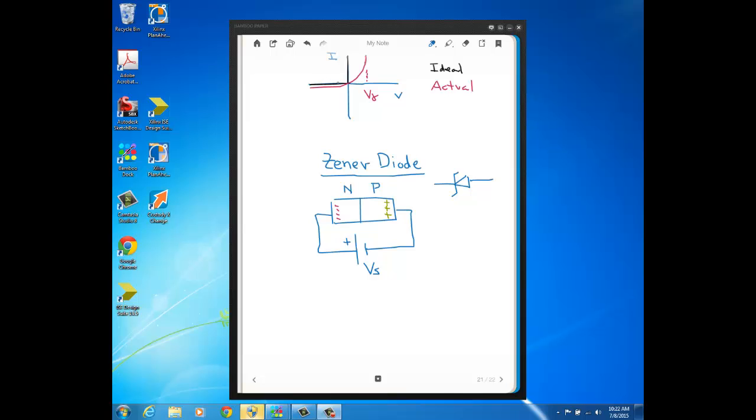voltage is. Now in the actual case, like we've gone over, the primary difference is what happens on the forward bias side, which is that the diode doesn't turn fully on until there's this forward bias voltage that's indicative of the energy required to overcome that electric potential barrier at the junction that we went over. So again, this V gamma, that would be the 0.6 volts or 0.7 volts for a silicon diode.